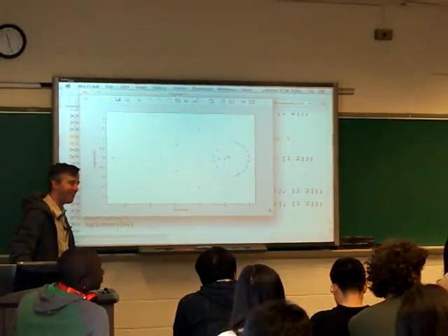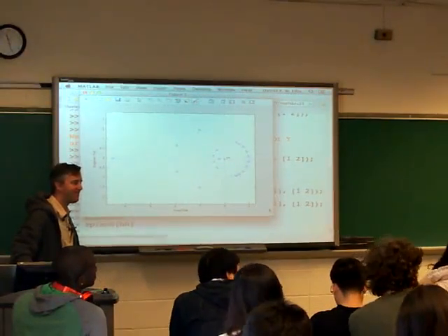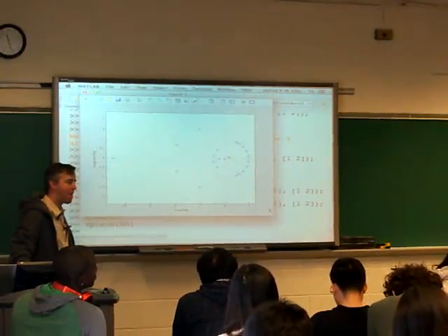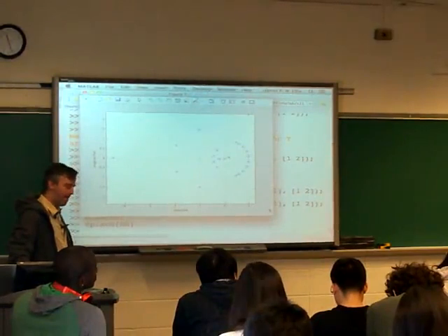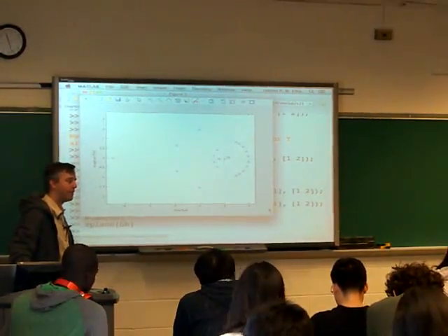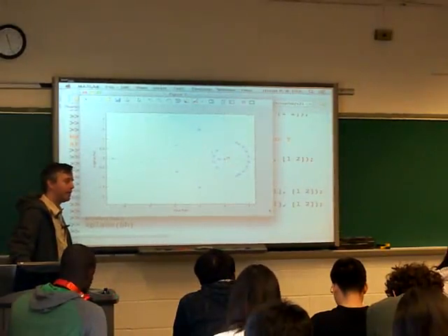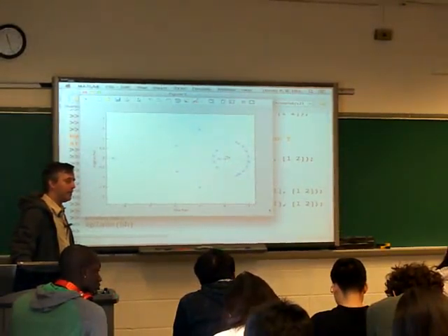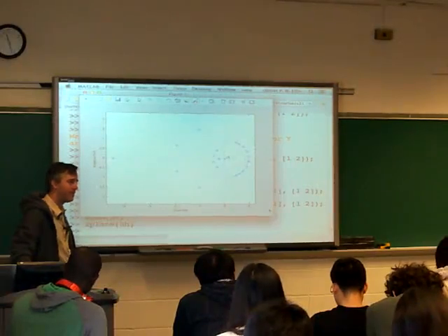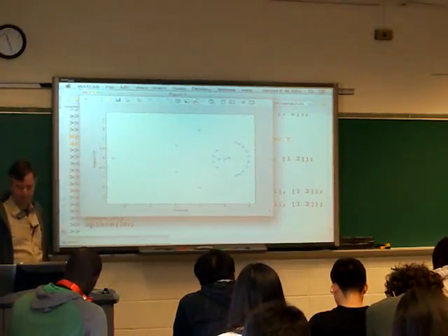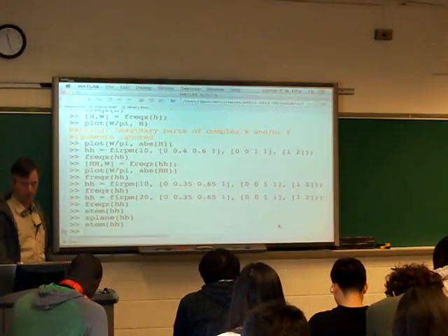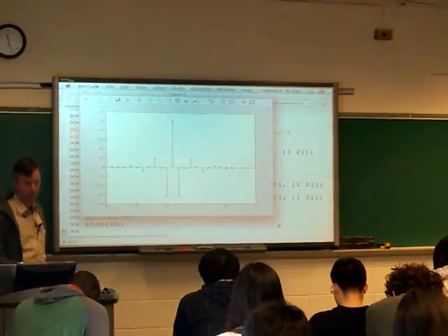Yeah. So now let's say we have actually optimized the frequency response by using this algorithm to get the ripple exactly matching the pass band. So now going back to the time domain, will that affect the initial window we've actually chosen to get the filter? Now the time response should be very good. So the window we chose initially would no more be the exact one, because it might also vary.